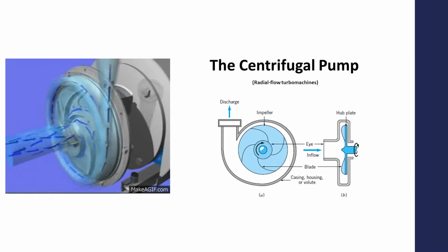So within the centrifugal pump, the impeller will be completely immersed in water, lessening the friction, little to no friction along the drive shaft rotating the impeller plate. And then through these blades is where the water holds and catches as being tossed around, then exiting the shaft, the discharge shaft. And on the cross section here on the right, it shows how the shaft gets slightly wider to have a greater head discharge or head outlet of the system, which would then just increase the amount of energy exiting the system.